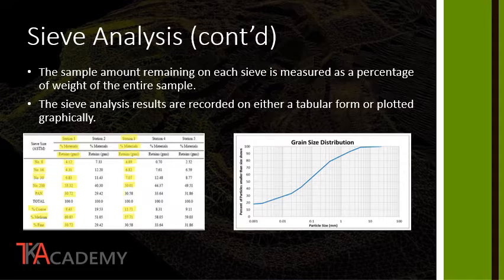The pan, or the amount that fell through all those sieves, was 30.58%, and that equals the amount of fine grade materials in that soil sample as 30.58%. So we have coarse material is 11.71%, medium 57.71%, and fines 30.58%.